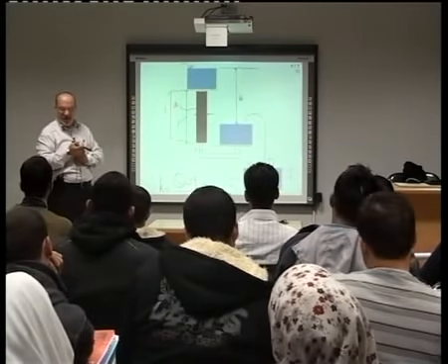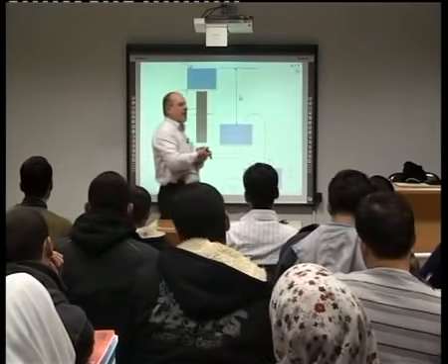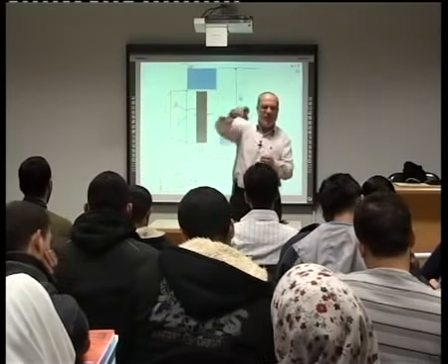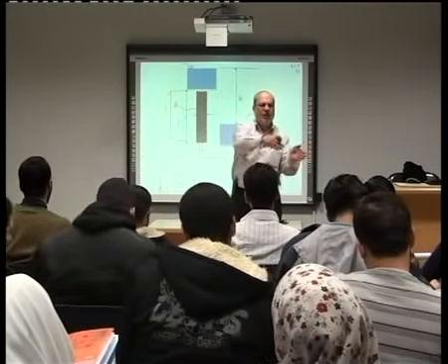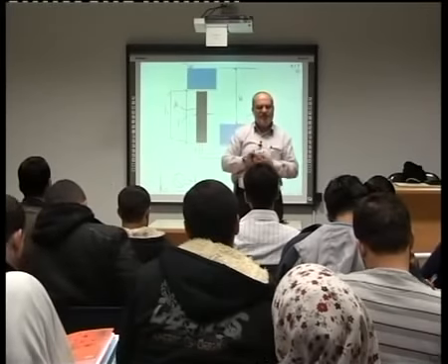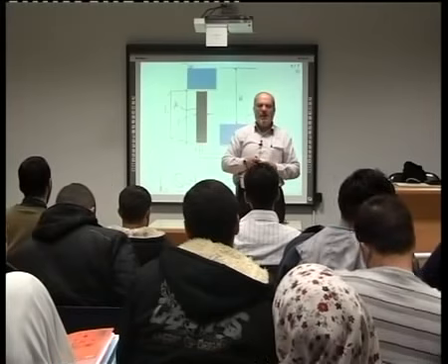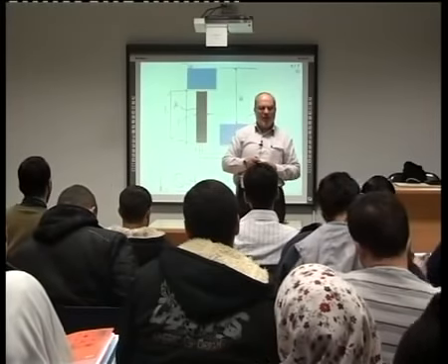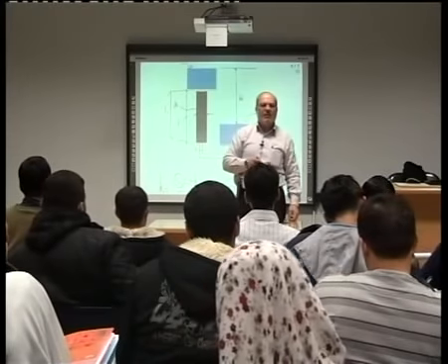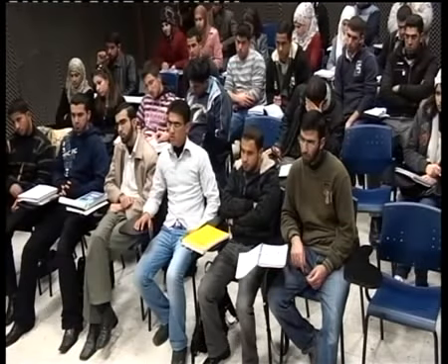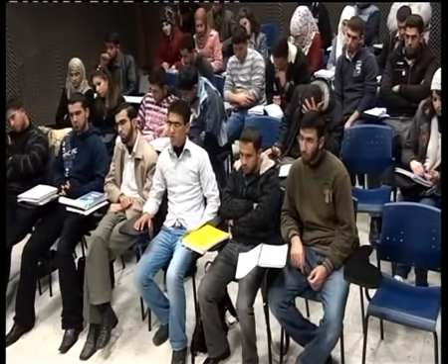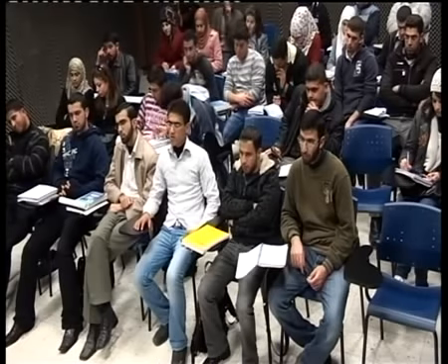It's very easy. But that test can be done for sand. Why? Because you remember, if you bring sand and you put water, immediately water will go through. In 10 minutes, you will collect a good amount of water through sand. But in clay, you may wait 1 hour to get at the end 1 drop or 2 drops of water, right? So this method can be used, but it takes very long time. So why not change it, to have another test? Okay, now we will go to another.